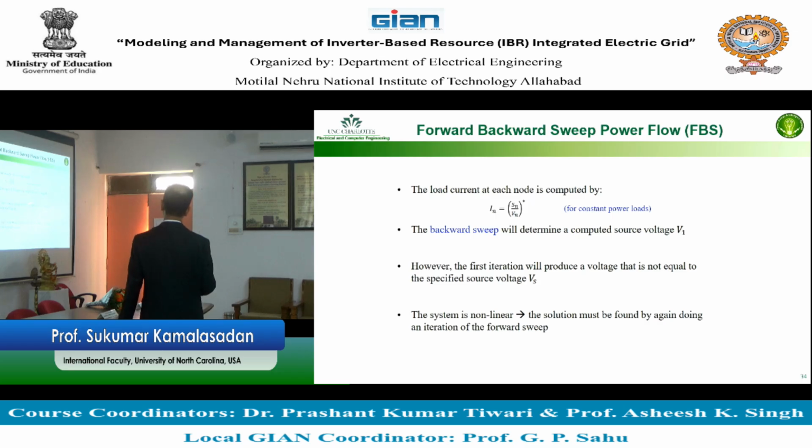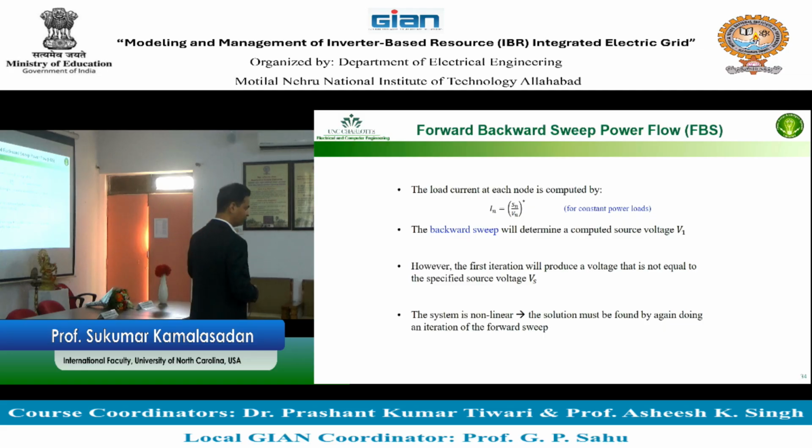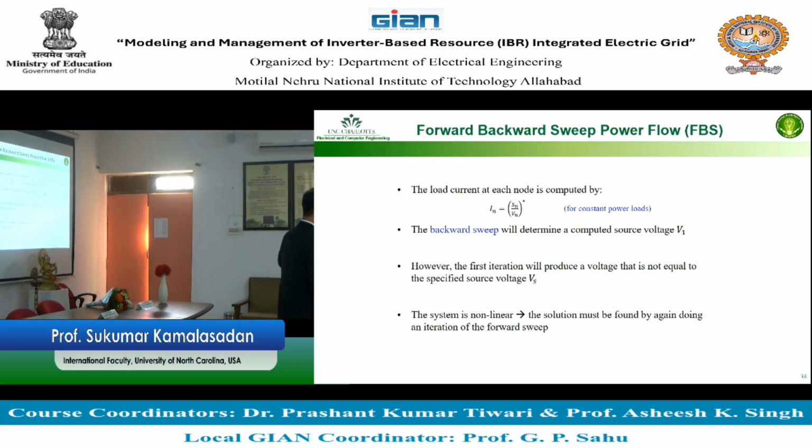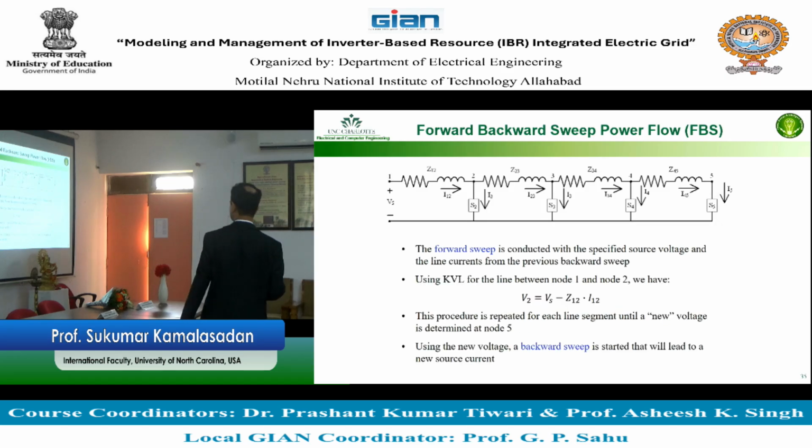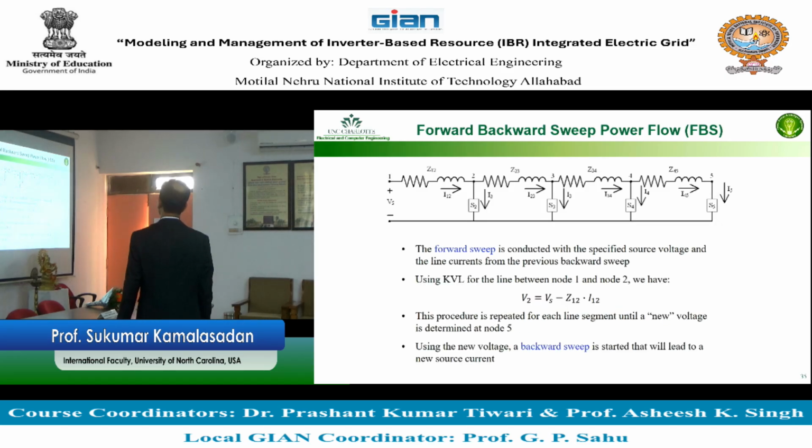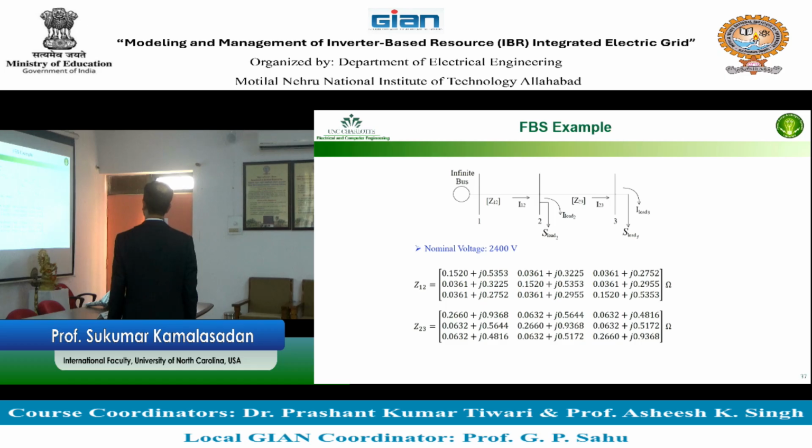And then after you compute, you go to node number 1. Once you look at the source voltage at node 1, you calculate the updated source voltage and you do this iterative sweep again. Oh, they are nonlinear in nature, but you don't have the problem of two equations and four unknowns because you are not running the generator side of the power flow. So we'll do maybe an example.